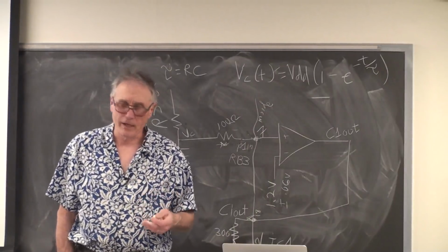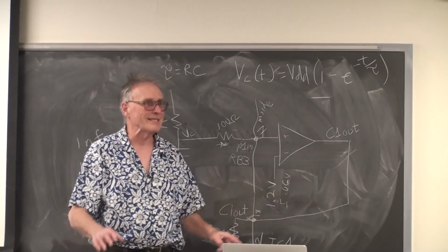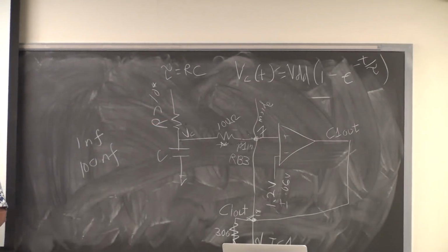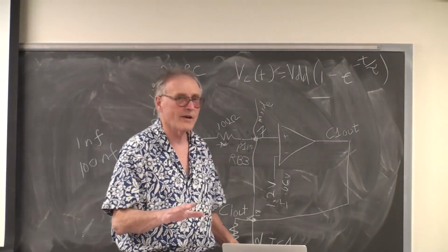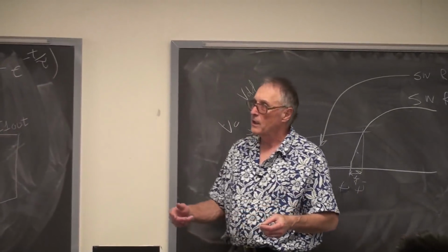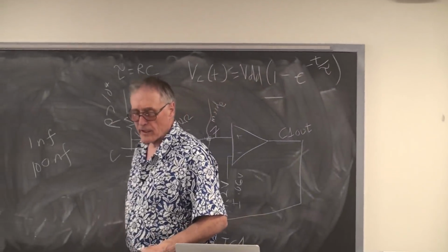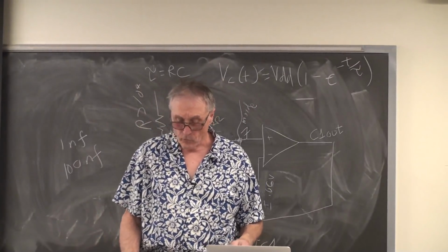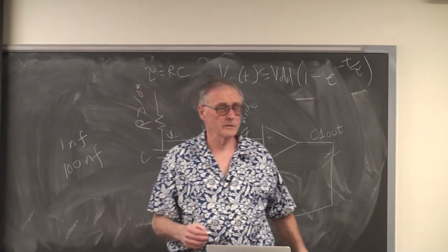You're going to need, however, to calibrate this 1.2 volts because plus or minus 0.06 is not quite accurate enough. So you're going to have to figure out a way, there's at least 3 or 4 ways of calibrating that voltage, of knowing what the exact value of the threshold voltage is. It might be 1.23 or 1.19. But that's a homework question also. Figure out how to get that voltage. Any questions on this?